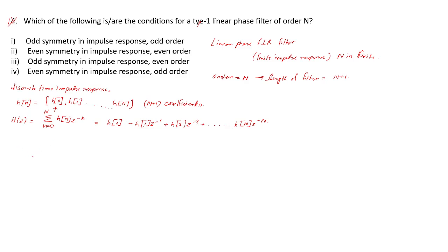They vary mostly in three aspects. The first one is the order of the filter, the second one is length, but that's not independent, you can consider it a derivative of order itself, because if your order is N, then your length is just N plus 1, so that's a redundant column, but I'm still writing it for better understanding.